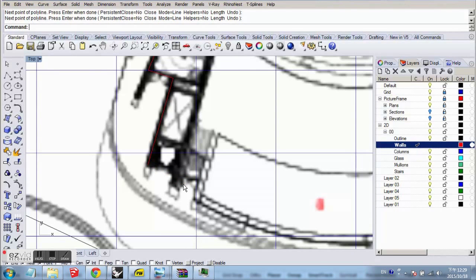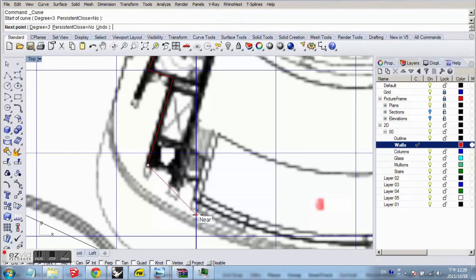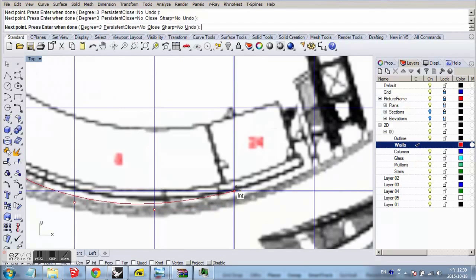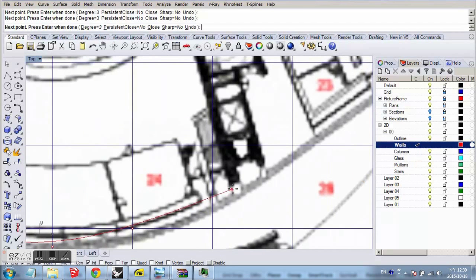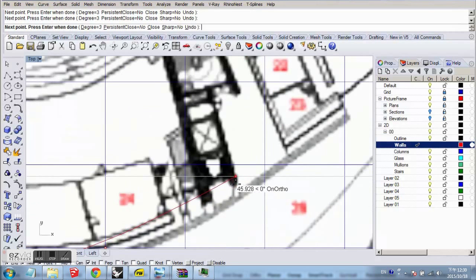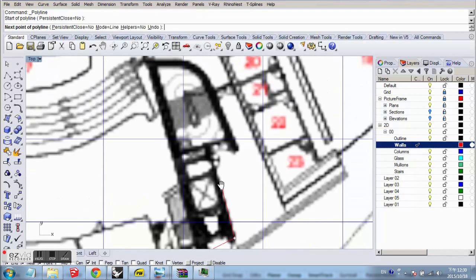We need to stop it at the curved part and from there onwards draw a control point curve. Alright, nice. Finish the curve with another polyline ending at the same grid line we started our shape with.